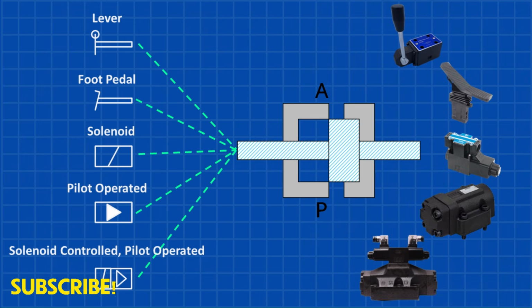So how do we operate a directional valve? There are several common methods to accomplish this, including levers, foot pedals, solenoids, pilot-operated systems, and solenoid-controlled pilot-operated. Each method has its place in the industry, chosen based on the size of the valve and the system's requirements.